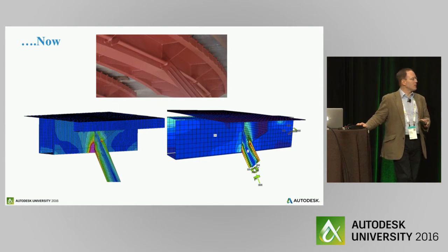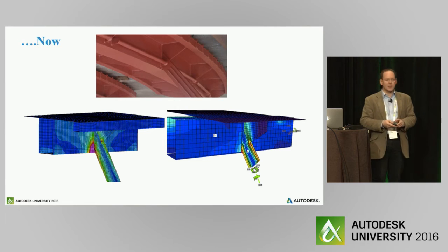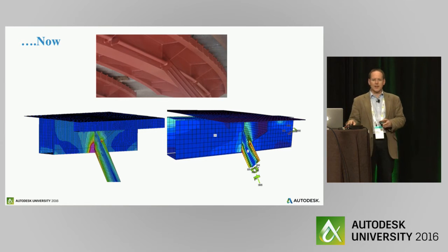Part of the problem of enveloping results, as engineers, you probably grapple with this all the time. You have to either envelope all the results and provide one set of forces, or you look at all the possible load combinations, including pattern loading. So here, the tool is able to go through each and every one of those load cases very quickly, and so we use that to help home in on which were the most appropriate load cases to consider in more detail.